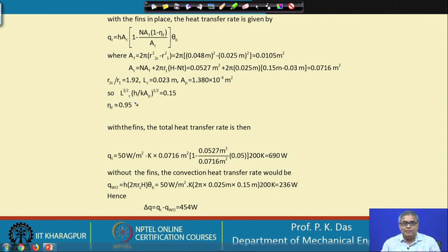So, you see we have taken many examples and calculated the fin efficiency, and we are really getting, never have we gone below 50%. So, we are really designing fins which have high efficiency. In fact, what fin efficiency we take or design will of course depend on the application, but rarely do we go below 70-75%. We generally go for higher fin efficiencies.